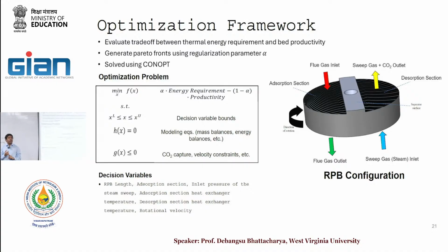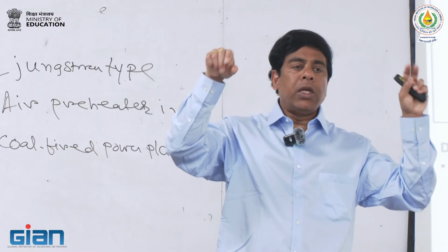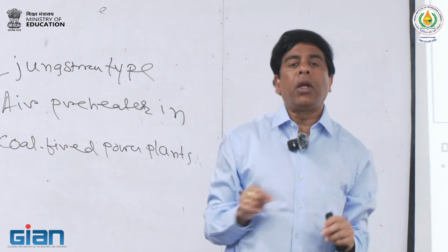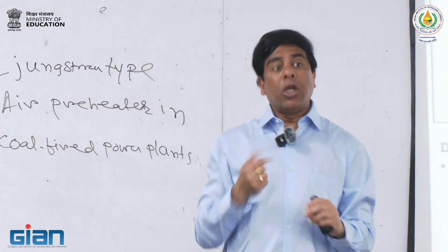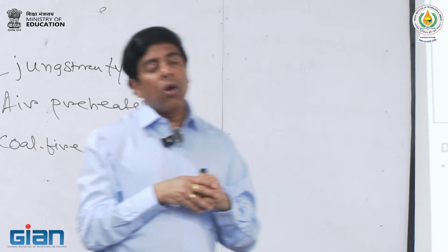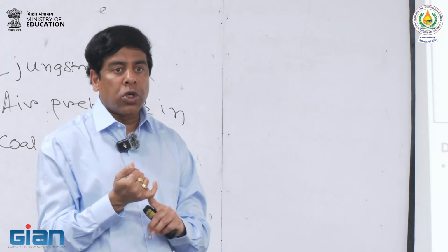This issue is there when you are treating flue gas from a coal-fired power plant, because that gas has ash and solids and all of that. Depending on the technology and the country you are talking about, there is always a suspended particulate matter emission standard that you are following. So you are already probably considering an ESP, like electrostatic precipitators, water scrubbers, and things like that.